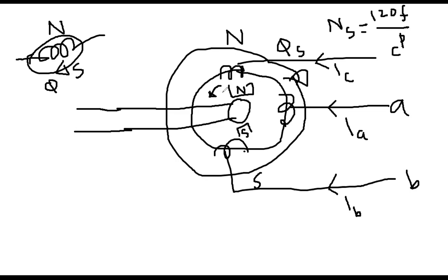Repulsion, not attraction. Then everybody see, once this south pole is aligned here, like this is south pole and then this will become north because this is rotating. So what will happen? This south and this north will be attracted. And because this is the direction of rotation of the internal field, the North Pole will be attracted a little bit in that way. So it will be just a little bit attracted, but cannot fully go.